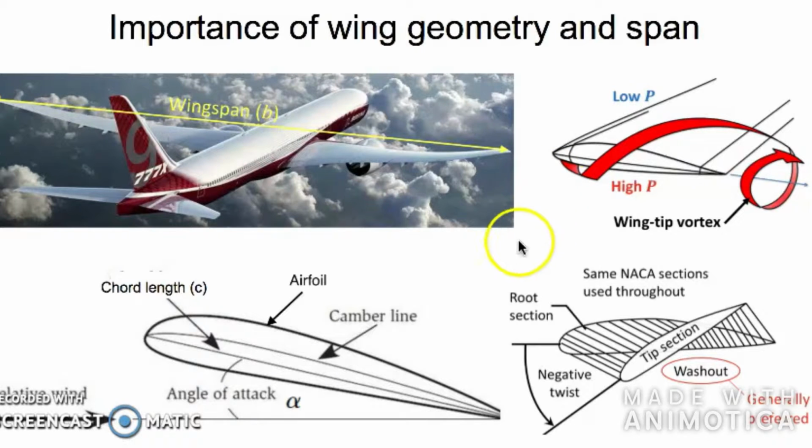The angle of attack, usually given by the letter alpha, is the angle at which the airfoil penetrates the airflow. This angle can be different depending on the position along the wing. If the angle of attack is smaller at the wingtip than at the wing root, which is close to the fuselage, then it is called a washout. This angle can therefore be a function of the position along the wing's length, and this is very commonly done on aircraft so as to improve the plane's stability.